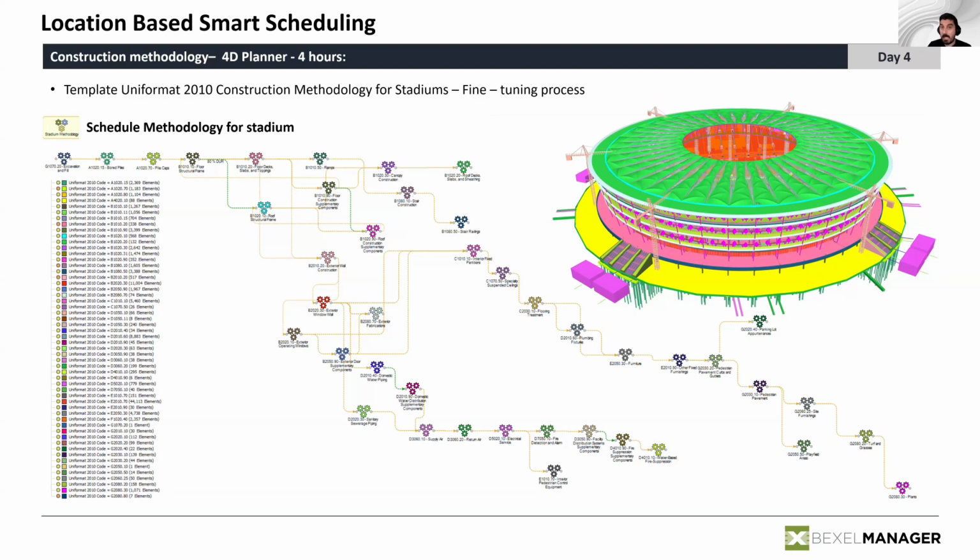That means that we go back to our knowledge base and say, okay, we have data enrichment tables that specify that, let's say, if the model element is a slab, and it is a concrete slab, a structural slab, it should get the classification code for the structural slab from UniFormat. So we had predefined steps in order to quickly enrich the model.